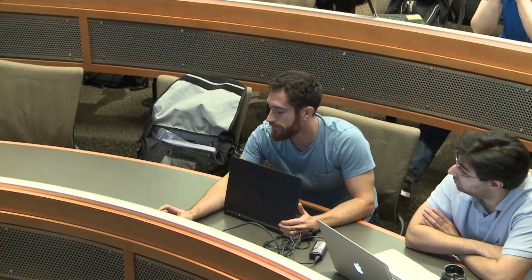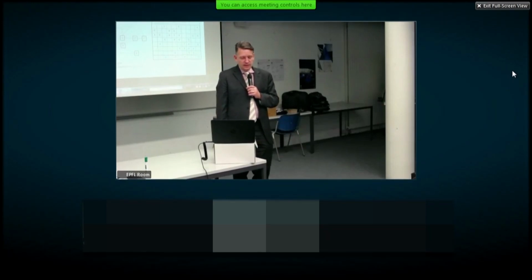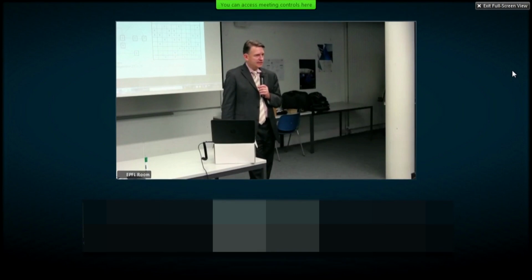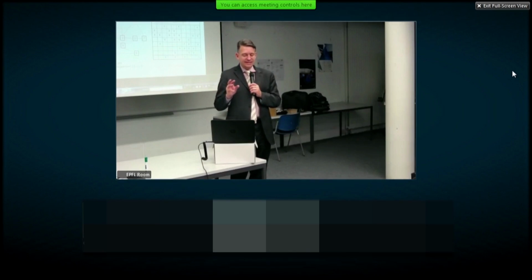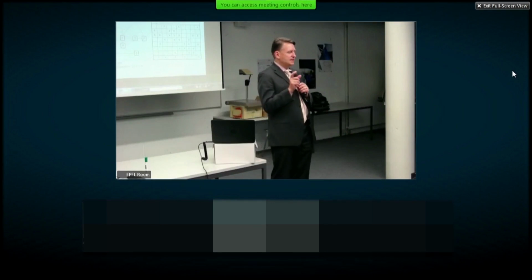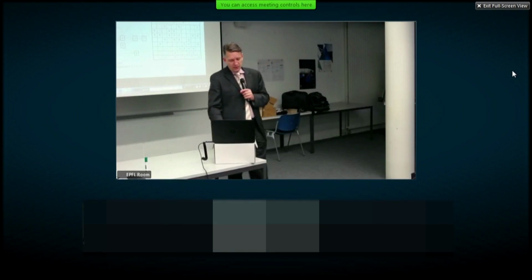No, there really isn't. The tricky thing is if it's a very complex system, like if we did the liaison diagram for the 84 by 84, let me just go back here, it would be pretty messy. So you want to lay out the liaison diagram so you minimize the number of crossing lines, for example. There are some graph visualization algorithms that try to create as clean a graph as possible. One of those is called a spring energy algorithm. It basically treats these links as though they were springs, and depending on how far apart things are, there's spring energy, and you want to minimize the total energy of the system. By doing that, usually the graph looks pretty clean. But there's no inherent meaning in how you lay it out. Does that make sense, Sam?